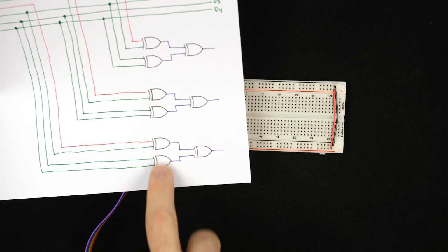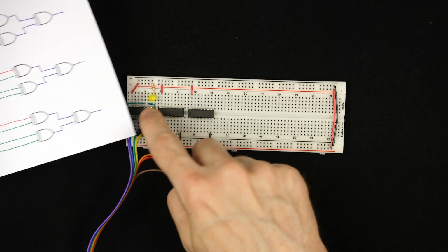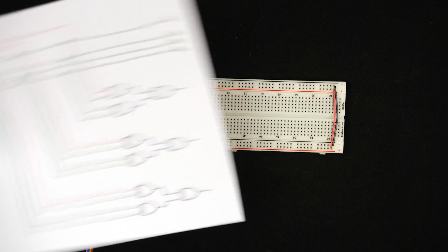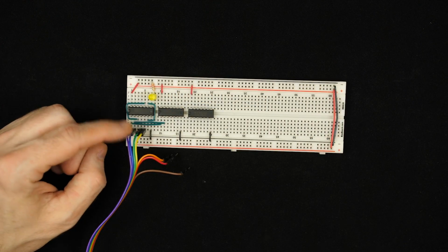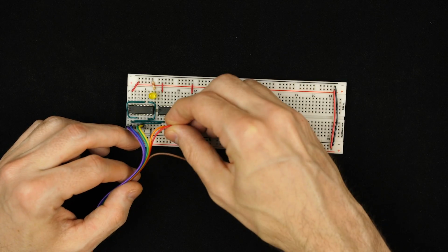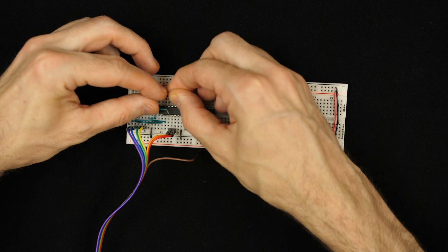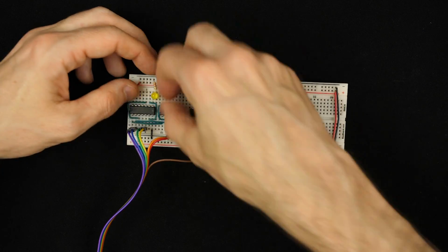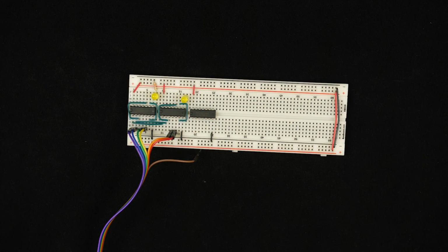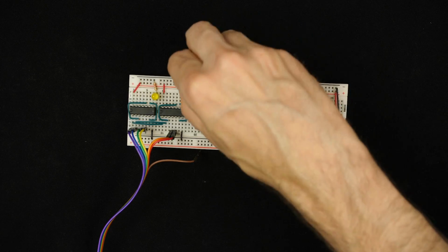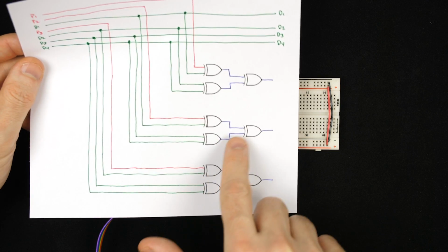So that's this bottom one here. So we've got those 4 inputs coming in, going through 2 XOR gates, and then the outputs of those going through a third XOR gate, and then we've got this LED looking at the output. So next I'll hook up these XOR gates. Two of the inputs are these 2, and then the other 2 inputs are the next 2 here. Hook those up there like that. And then again, the outputs of these 2 XOR gates on the bottom are going to go around to the inputs of an XOR gate on top. And then the output of that XOR gate on top, we'll stick an LED here so we can see what's going on with that. And so that's the second one here.